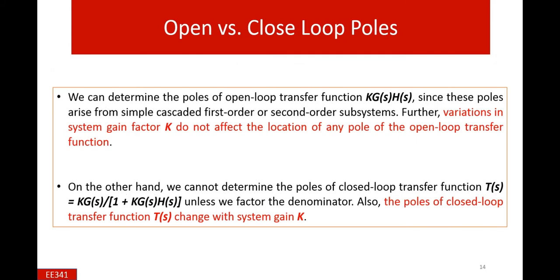Actually, Root-Locus is the path of closed loop poles. With the variation of k, the position of the open loop poles does not change. The position of the open loop poles is the starting point, and the closed loop poles change accordingly. The closed loop poles change when the value of k changes from some minimum value to some maximum value.